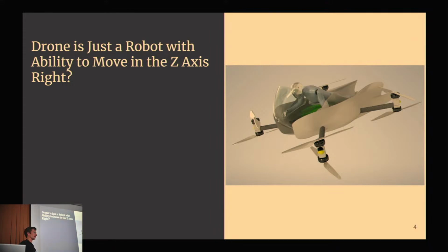For example, if we see the drone moving forward, we are able to manually make it go back. If it's leaning to the left, we can see and react to this and make it roll to the left. And in smaller drones, it is not possible for a human to intercept this fast loop of control.